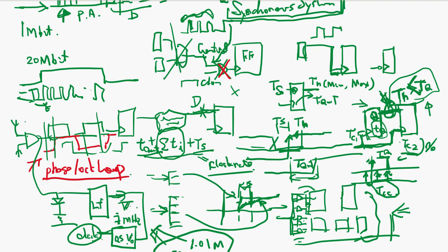And for the incoming clock, after detecting this edge, you use the AND logic and get the low pass filter output to reflect the difference in the phase as a DC voltage level.